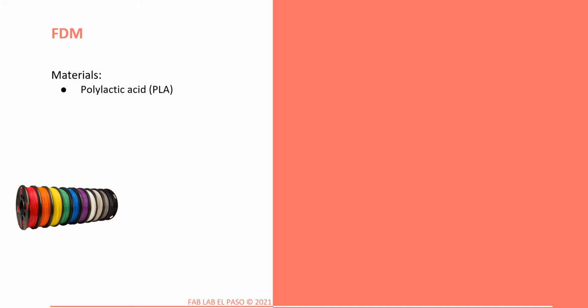Materials available for FDM printers include an incredibly wide range of thermoplastics. Standard plastics like PLA, which is a biodegradable plastic made from cornstarch, is one of the most popular and least expensive choices of material. ABS is another popular material, and is actually the same material that Lego blocks are made from. These types of plastics are used for non-critical applications. Engineering plastics like nylon and TPU are often used for structural applications, and advanced plastics like Ultem and PEEK are used for mechanical, thermal, or high-strength applications.